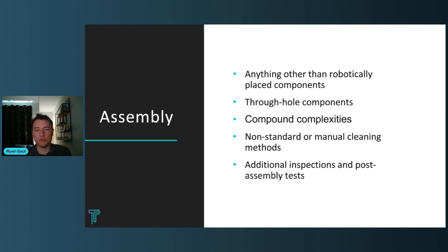So consider what pressure you're putting on the wash process when you are choosing components that would be damaged or destroyed by wash. And the solution is, in many cases, a relatively manual one, which will add significant cost. And then, of course, additional requirements on the inspection and testing side. Post-assembly is always going to add cost.